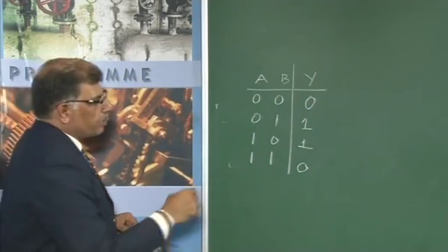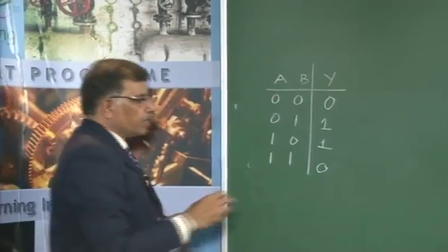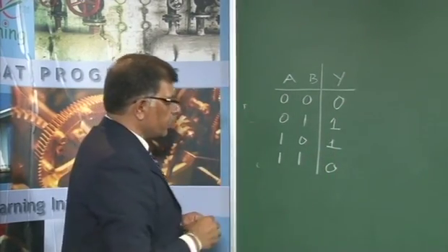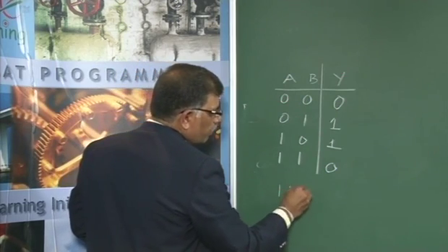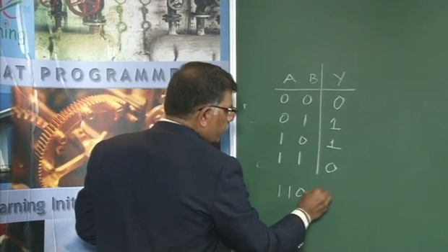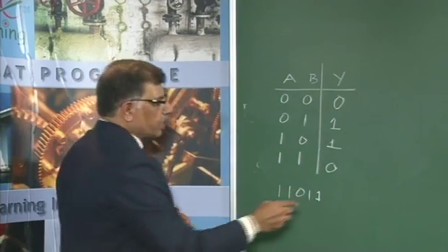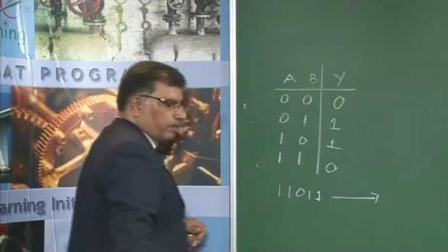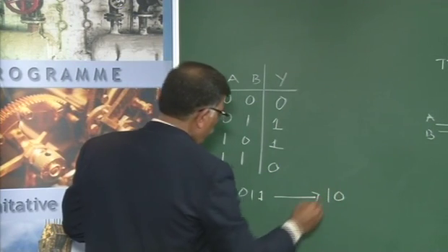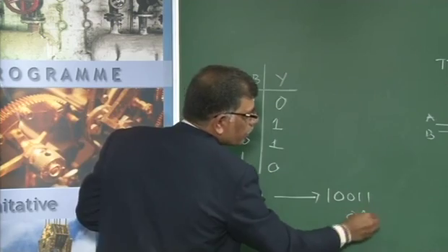This gate has significance in communication systems, particularly to check whether there is any error in the output transmitted from the transmitting station. For example, if I want to transmit 1001, they will add a parity bit such that it becomes even parity information, which is transmitted to the receiving station. If any change occurs, suppose this bit is changed to 0, giving 1 0 1 1, the parity is now changed; the parity of this is odd.